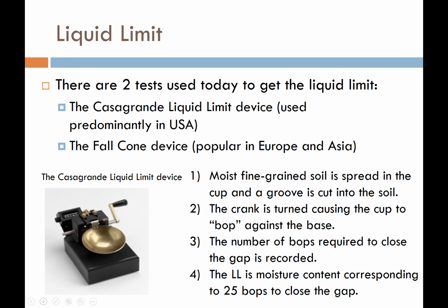So first we can talk about the liquid limit. There are two tests used in the world today to measure the liquid limit. The device or the test that I was referring to earlier is the test in the Casagrande liquid limit device. That's this little device down here that I circled. So you can see there's a little cup that we place the soil in and flatten it out and make a little soil patty.